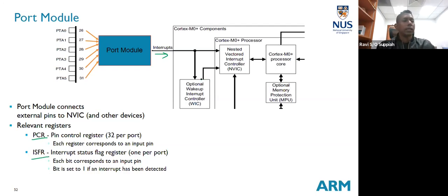That is basically how the peripheral blocks send the interrupt request over to the processor. So the NVIC is the middleman. It takes in these requests from the peripheral blocks, looks at all the requests and the priorities, and decides how to manage them.